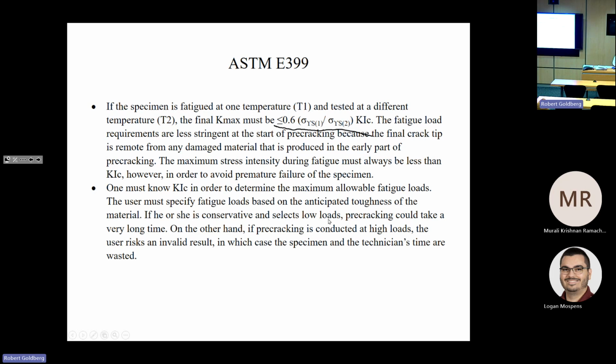And at different temperatures, you'll have different yield stresses. So keep K max less than or equal to the ratio of your yield stresses multiplied by your expected K1C. This will again help to ensure that you're staying within the specifications of the test.